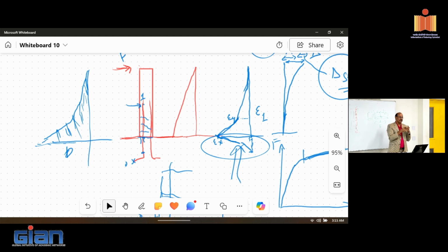So you calculate the equivalent viscous damping, and then they say, okay, this structure survived because it was able to develop plastic action. They calculated the damping and said it's equivalent to 25% damping, so in the future we need to put in 25% damping. But that is an integral part: the damping is inherent, coming from the flexural action the column went through. Nobody really looked at the minimum damping needed. What they knew was that the 3%, 5% inherent in an elastic structure is not sufficient.